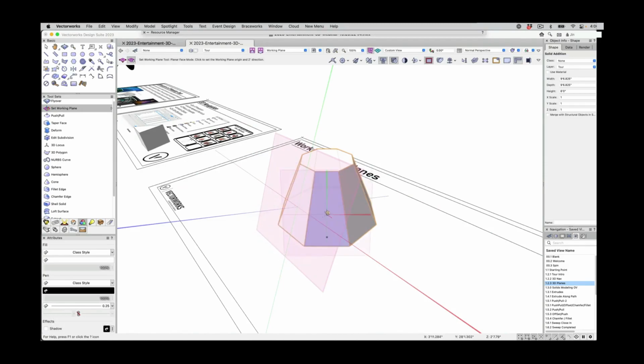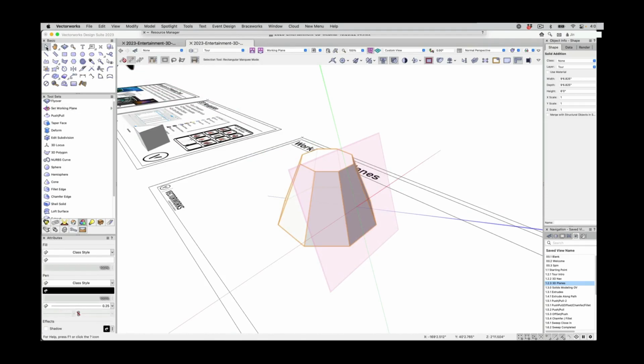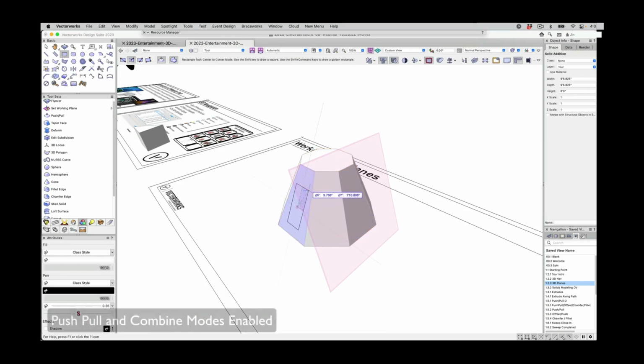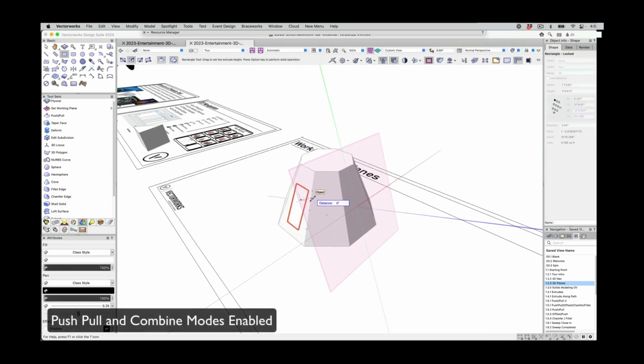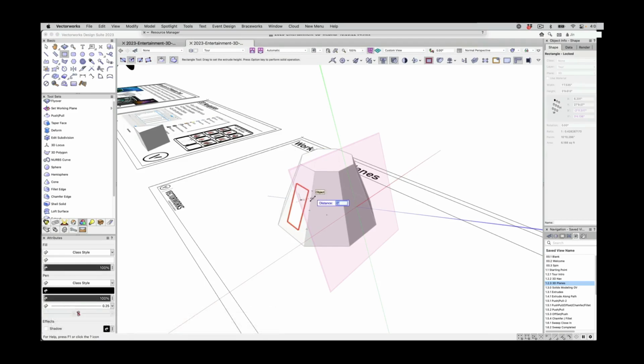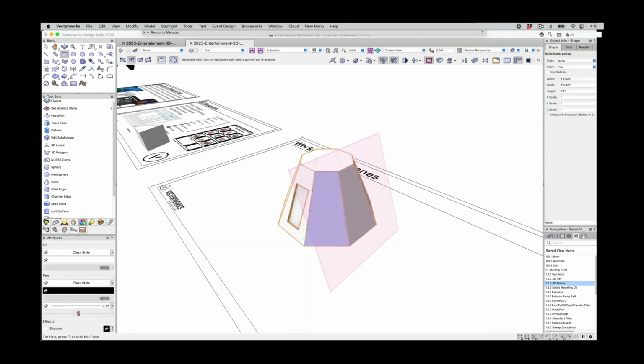And the second is the planar face mode, where we can just select any plane and it'll automatically align to that. There's another option with some of the select 2D tools. In the navigation bar, we'll find automatic. And when using things like rectangles or circles, it'll automatically work on those planes. And there's an option in the mode bar to go into the push-pull and the solids operation directly from that.